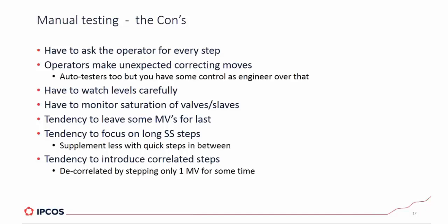Of course, while manual testing, we have to watch the levels extremely carefully. And depending on the size of the capacity that we are talking about, this could be a very time-consuming exercise. We have to monitor the saturation of valves and of slave loops ourselves all the time.